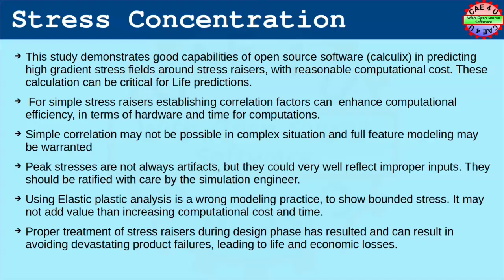Peak stresses are not always artifacts, but they could very well reflect improper inputs. They should be ratified with care by the simulation engineer. Using elastic plastic analysis is a wrong modeling practice to show bounded stress levels. It may not add value other than increasing computational cost and time. Proper treatment of stress during the design phase has resulted and can result in avoiding product failures, leading to life and economic losses.